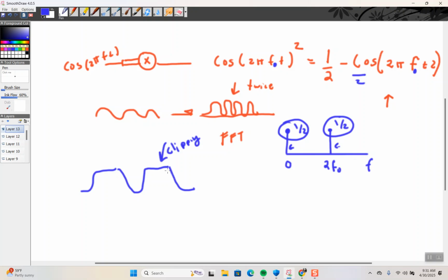Well, these discontinuities will be easily picked up by having infinite spectrums. So if I see two, it's great. If I see extra things, right, then it's not working. And when you measure the things you don't want versus the thing you do want, that's total harmonic distortion.